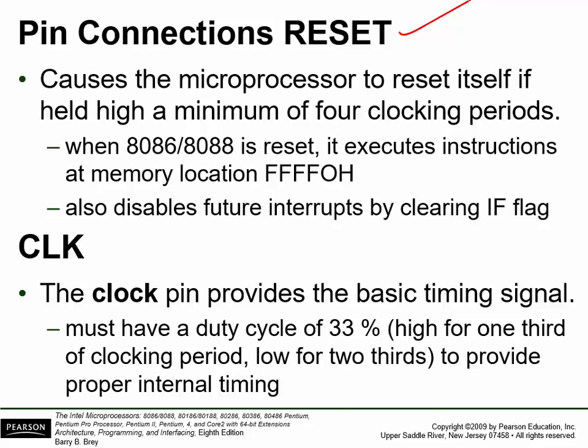This particular processor used a clock manager, and as a result, the clock manager handled the reset. But most microprocessors have done away with that and are using active low. One of the things that's important is that there's a start address. Reset starts at address FFFF0. That's the starting address, and you've only got 16 bytes there, so it's usually a jump to main.